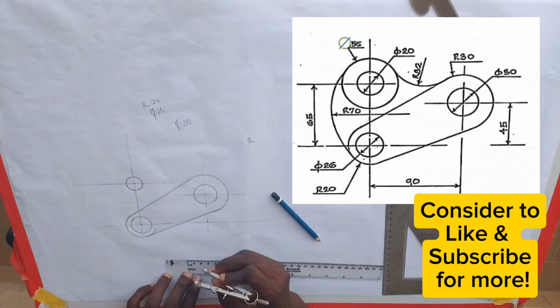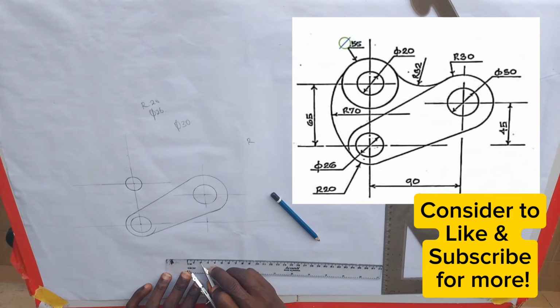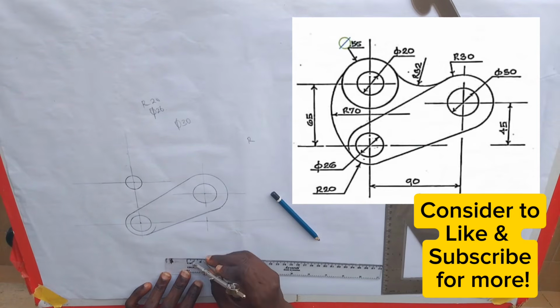From here to here is 10 millimeter, which is 1 centimeter. Here is 2 centimeter, that will be 20 millimeter. Here is 25 millimeter, and that will be 2.5 centimeter. But we are looking for 2.75. So if here is 2.5, here will be 2.6, here is 2.7. So in between 2.7 and 2.8 is 2.75. So I will place it here.